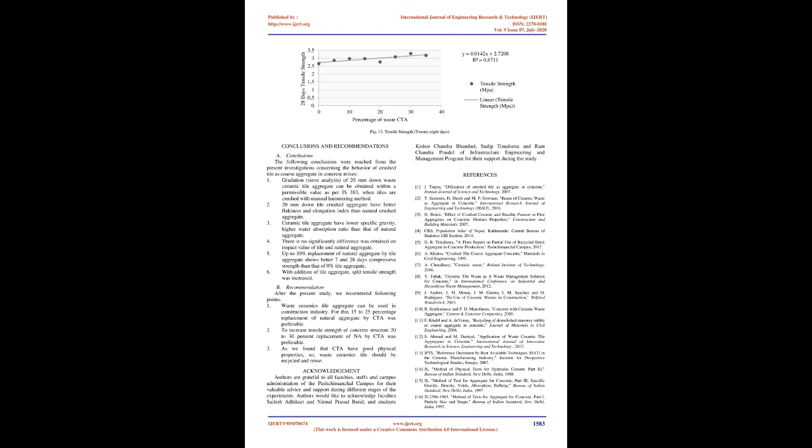W/C ratio was decreased by decreasing the aggregate quantity, i.e. increase in cement to aggregate ratio. W/C ratio of mixes is taken below 0.5 for all types of mixes.